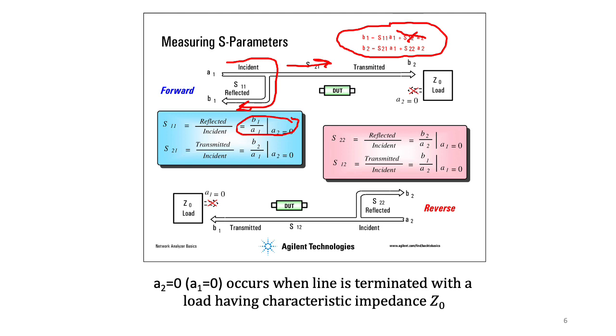That's quite different and much easier to perform at microwave frequencies than measuring the input currents or output currents at RF frequencies. So the S parameters are particularly useful for measuring distributed systems where the frequencies may be so high that parasitic inductances and capacitances become a very important portion of the measurement process. Here the reflection is set exactly to 0 whenever the impedance of the load matches the transmission line characteristic impedance.